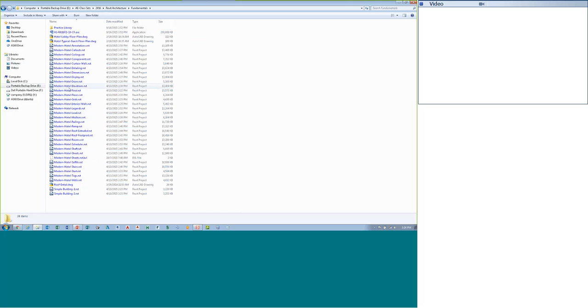and I double-click the file, what is going to happen is that Windows operating system is going to look at this file extension and go find the Revit.exe file, any Revit.exe file. So it may not default to the latest version. It may be defaulting to an older version. And so you're going to run into hiccups and problems. So you don't really want to do that.